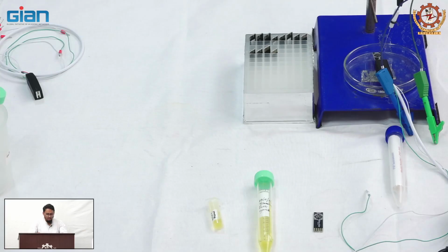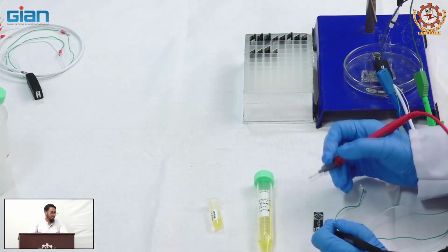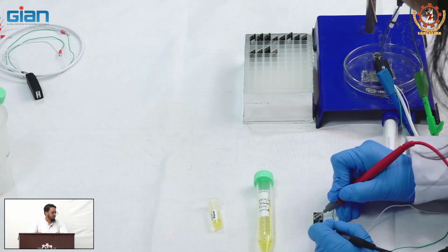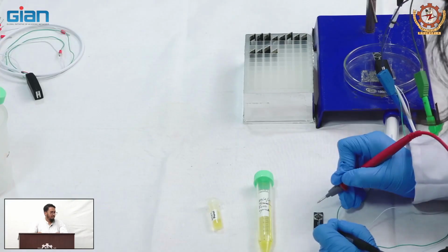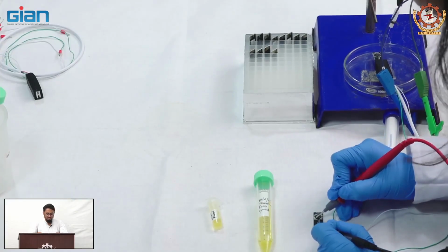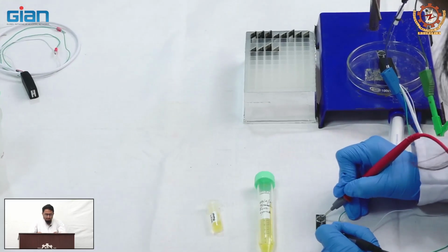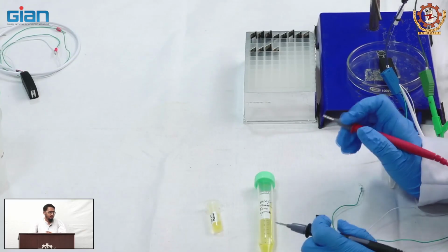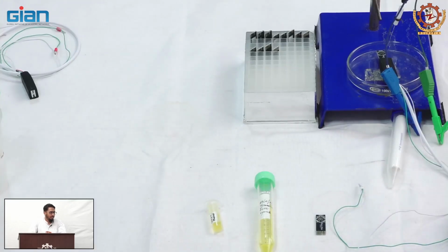So before we start electrochemical testing of the working electrode, first we will do just a connection test to make sure that the PCB based electrode is properly wired. So for this we will be using a multimeter and we will do a connectivity test. So the beep actually tells us that the electrode is properly connected. So as you have seen on the screen, the testing is successfully done. So now we will move on to test the working electrode electrochemically using cyclic voltammetry.